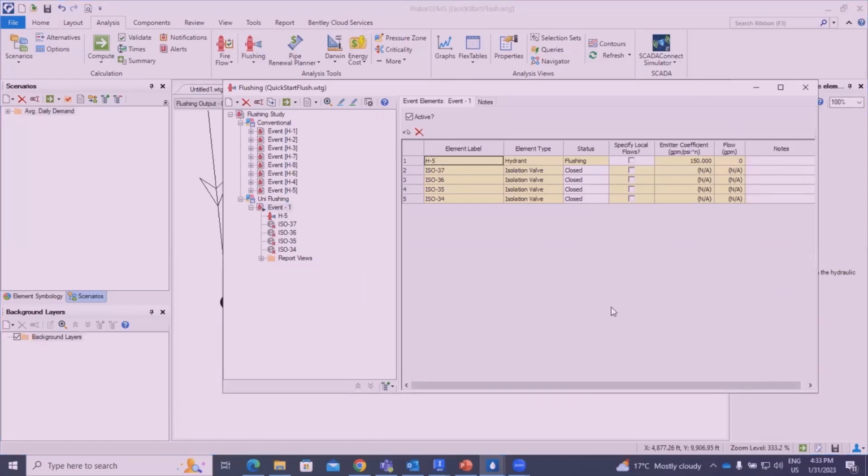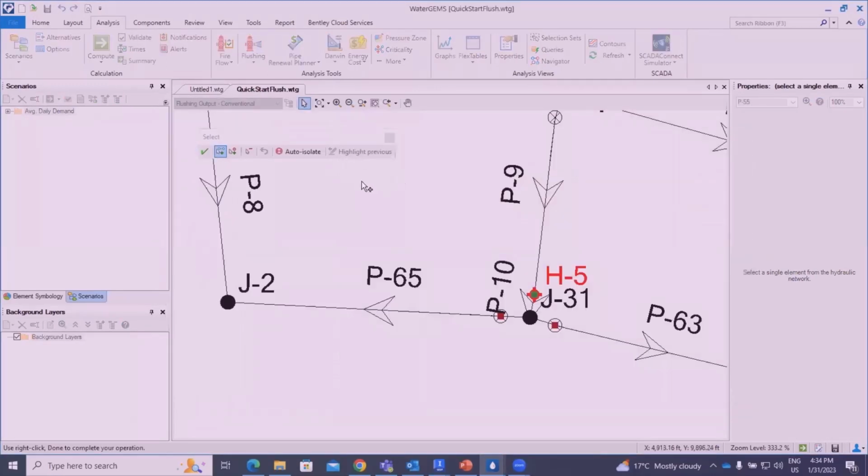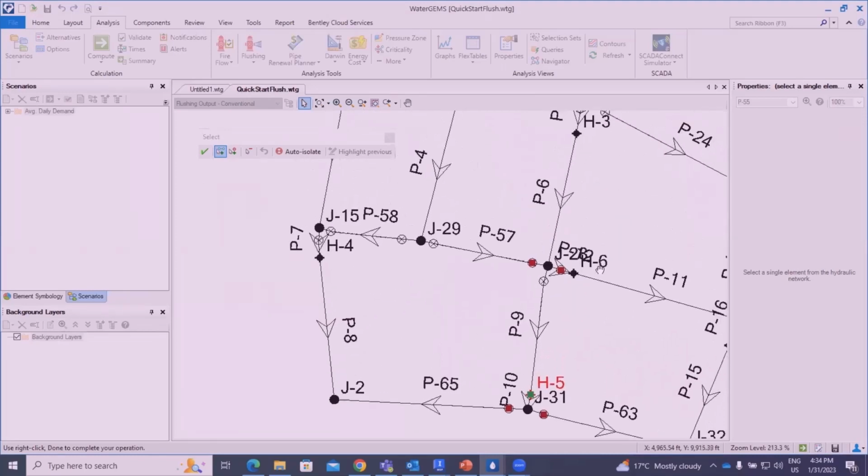So feel free to add some respective notes to the element if you want here. Now, next thing we have to do is identify the pipes to be the part of the pipe run. So by picking the select from drawing button on the right pane, here we can select it. Once we select it, then we pick the option this one, and we're going to select the pipe which is attached to the isolation valve.